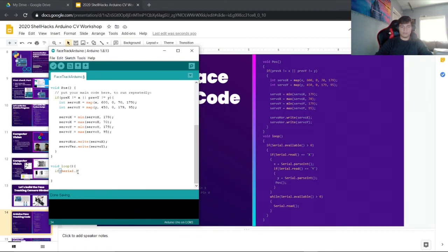So we're going to do Serial.available if it's greater than 0. Then we're going to check another if statement, and we're going to read that serial communication. Make sure to make the Serial a capital letter. The capitalization of the letters and the words actually really does matter when it comes to programming, especially with C. Not with all things, but with most things.